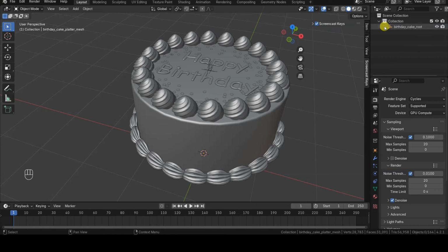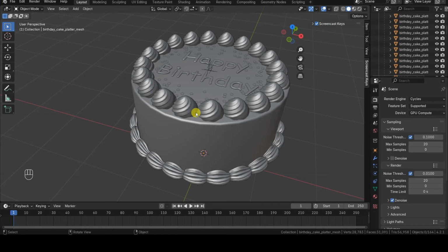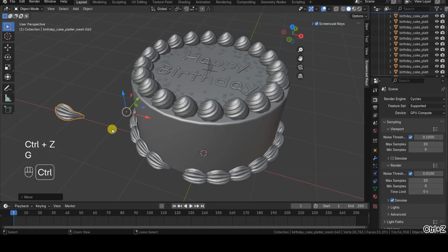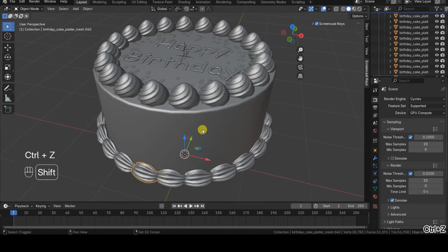The new objects created using separate will have their origin located where the origin of the original object was. So most of the time, you'll need to set their origins manually to avoid incorrect behavior with rotations or other operations.